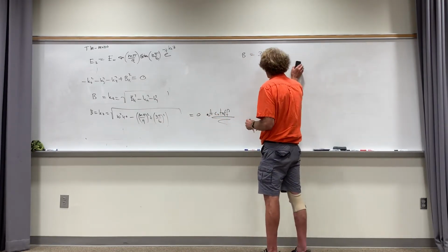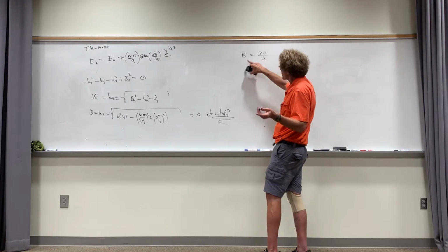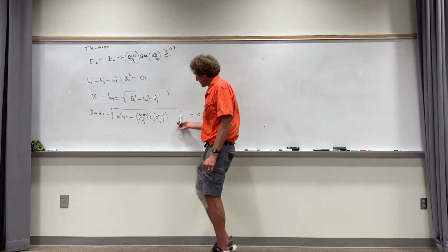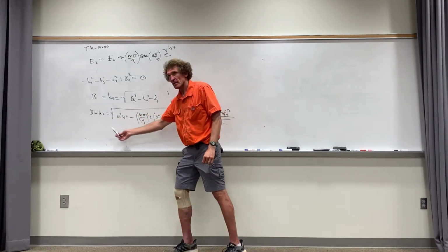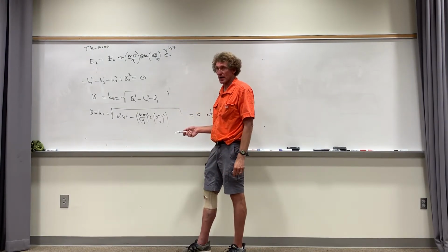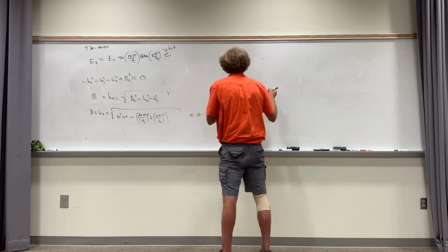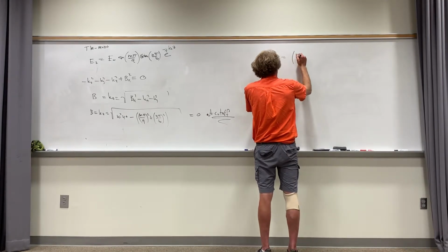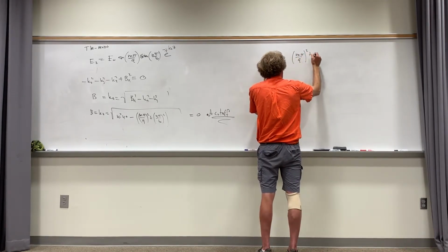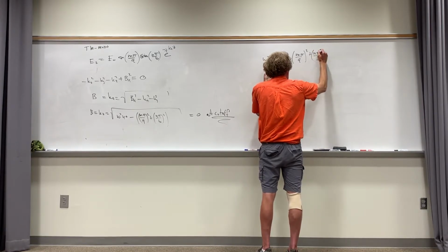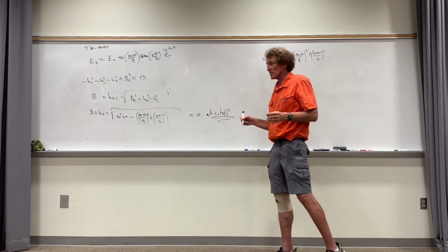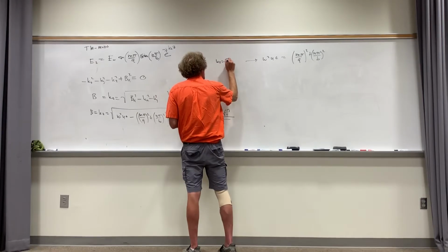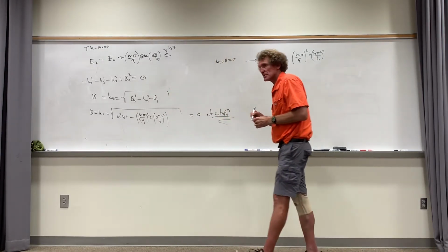So what is cutoff frequency? Well, it's when the wavelength goes to infinity, or it's when beta goes to 0. So how do I figure out what that amounts to? Now watch this. So I know this equation is 0, don't I? Right? I can throw the square root sign out the window, can't I, class? So now I have this. I really have omega squared times mu epsilon is equal to m pi over a squared plus n pi over b squared. The only thing I'm doing is this is the equation that happens when kz equals beta equals 0. This is at cutoff. And make sure you understand this. This is an important point.